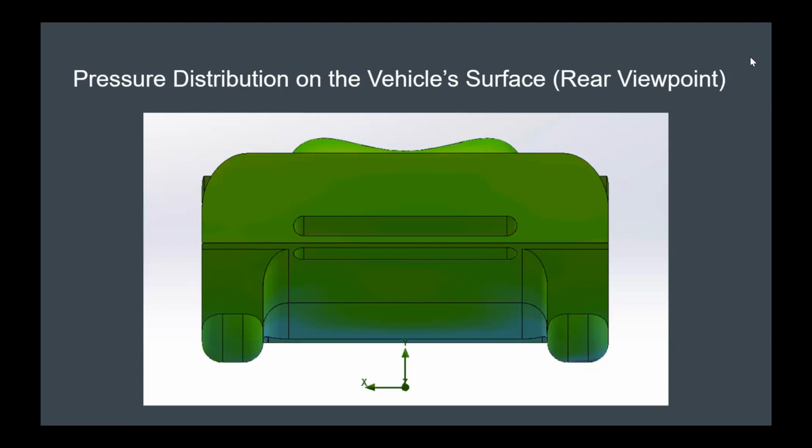And then here's our rear view. We added this hole into the back, right at the end of the diffuser, into the back of the car. This dragged air through the hole and up into the back of the car where the wake is, so we could hopefully disrupt the wake and low pressure region behind the car.